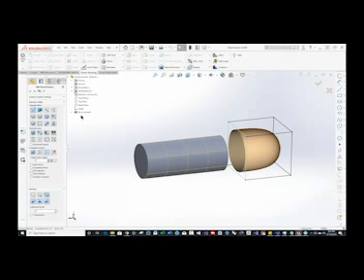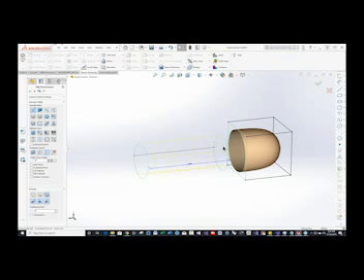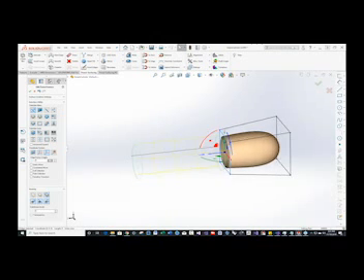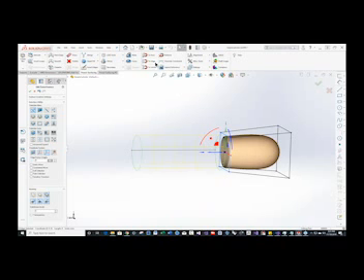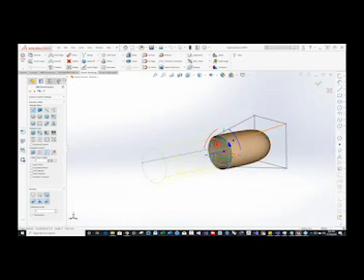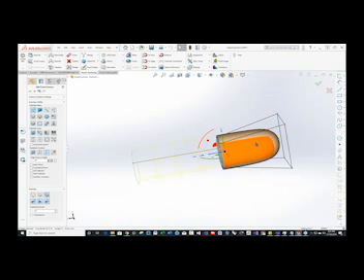I can go into this and turn that off, so now I can see through it. Typically what you want to do is get this kind of close. It doesn't have to be exact, but you want to get it close to where you want to constrain it. So we're just going to say constrain to an edge. What we've done is constrain that SubD surface to the edge.